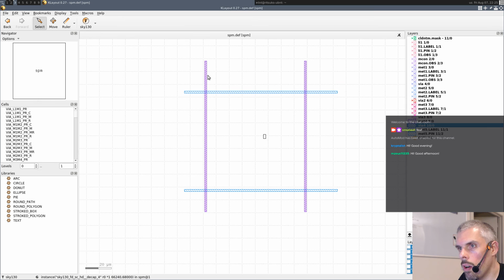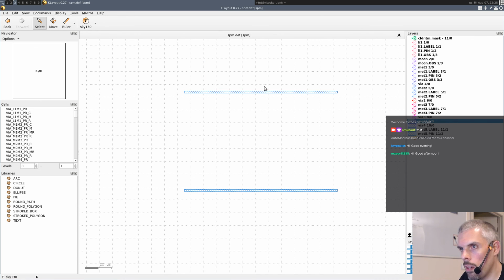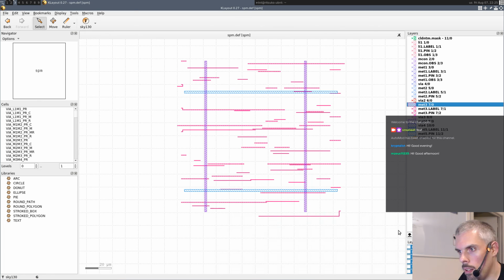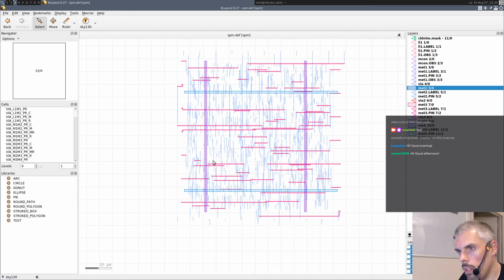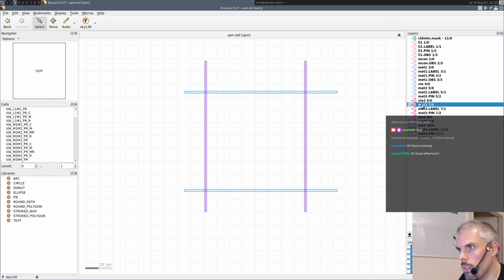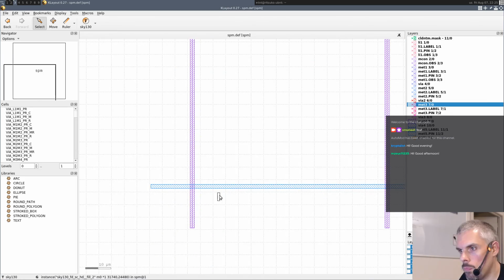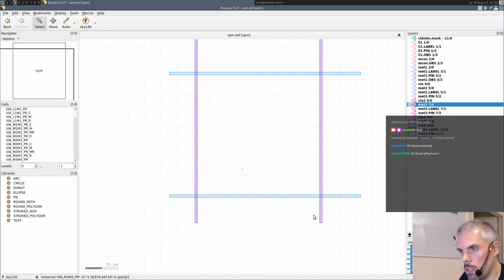In case you don't know, on the chip, things are routed like in a kind of old PCB, where you have one layer which routes all the horizontal connections, then another all the vertical connections, and then all of that repeats. Here, metal 5 is a horizontal routing layer. Metal 4 is a vertical routing layer. Metal 3 is going to be another horizontal layer. Metal 2 is going to be another vertical layer. That kind of stuff, right? It's the preferred routing direction. And metal 4 and metal 5 here are only used for power distribution.